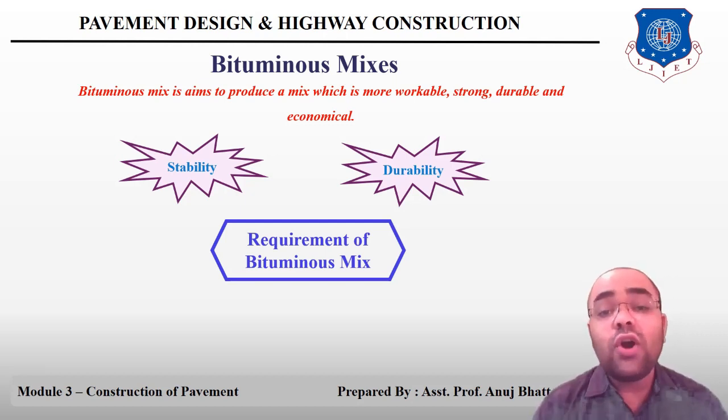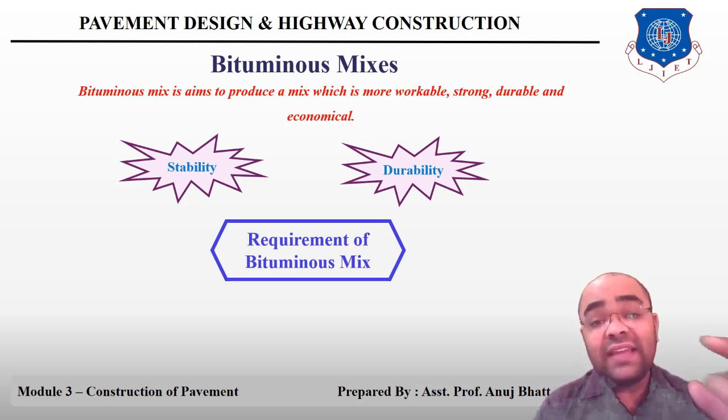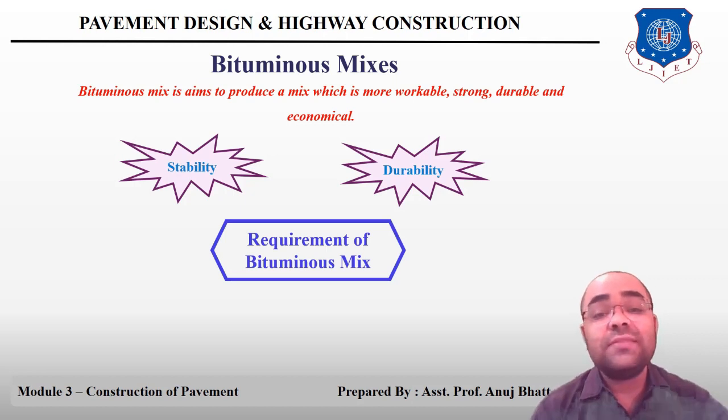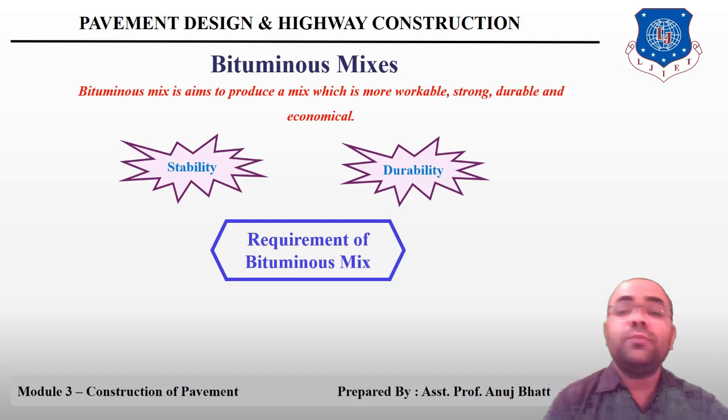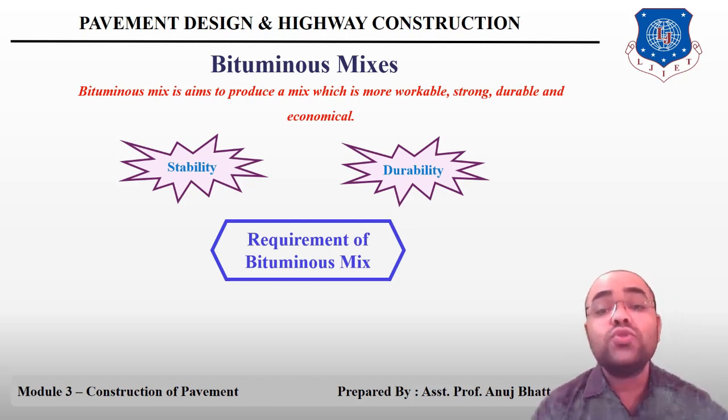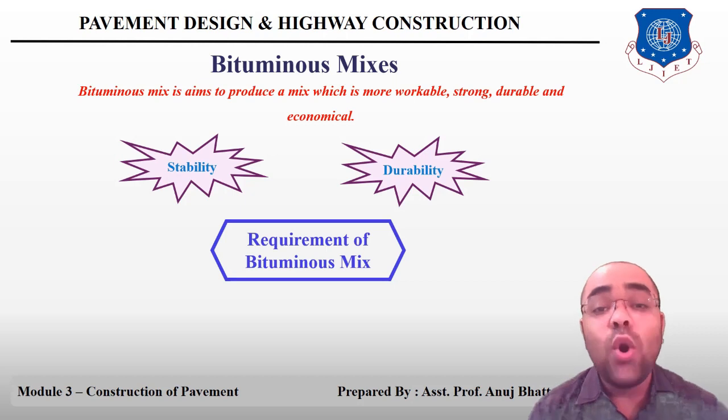Stripping is the loss of binder from the aggregate, and if the aggregates are exposed, the disintegration is minimized by high binder content, since it causes the mix to be air and waterproof, and the bitumen film is more resistant to hardening. So this is all about durability.